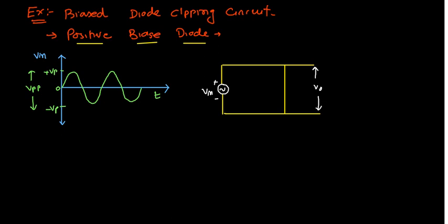Now let me connect the diode over here. I'm going to connect the diode over here, and this is V bias, and over here a resistance. So I'm drawing that resistance. You can give R, R1, whatever you like. This side I'm connecting the diode, but the direction of the diode is different this time. And over here I'm connecting V bias. So this is V bias. This is the diode. We are considering an ideal diode. And now we want to check what will be the output waveform.